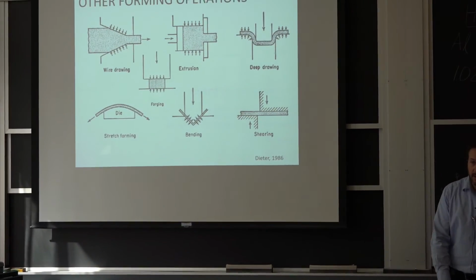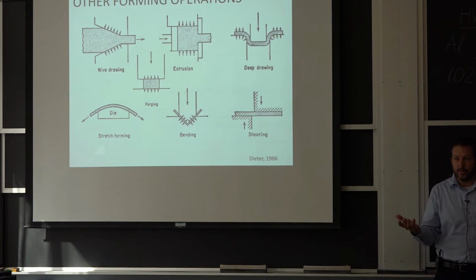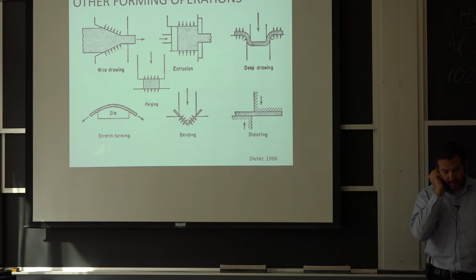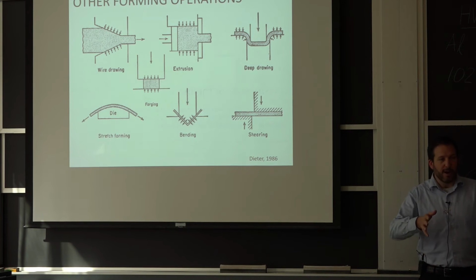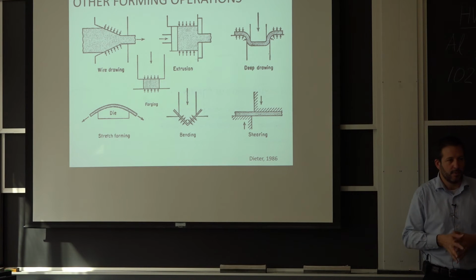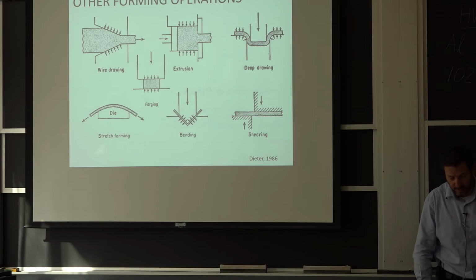Even if you try to make a prototype, you can draw in SolidWorks what you like, and you get these shops to make all these bends for you very, very precisely. It's become so much more automated than even 10 years ago to make almost an entire box out of one plate that's cut and bent into these different corners. So bending is a very useful process, and shearing is just for separating parts.